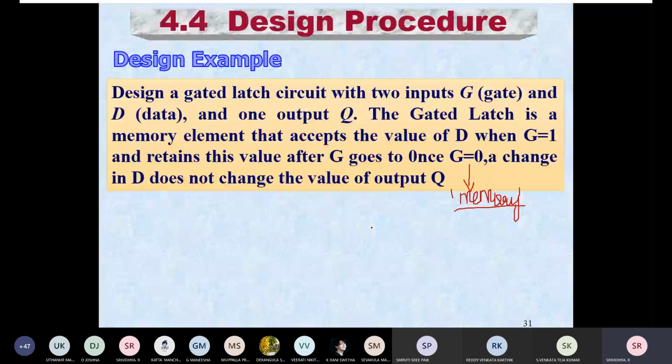See, ma'am, for any design problem, the main table you have to draw is your primitive flow table. If you have not made any mistake in your primitive flow table, then your final answer will definitely be correct. But if there is a mistake in your primitive flow table, that is your first foremost step, so your entire design problem will be wrong.